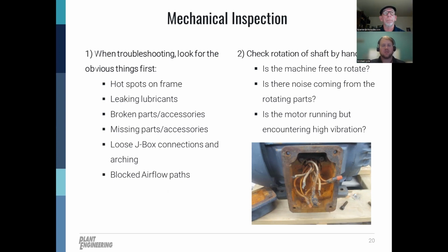That's not something that you want to just say, oh, well, the motor paint's going away. There's a problem inside the motor that's causing that. So if your motor has withstood enough heat to show signs of these external hot spots, that definitely gives us a good idea, even without opening the motor, of some of the degradation going on with the components inside the motor,